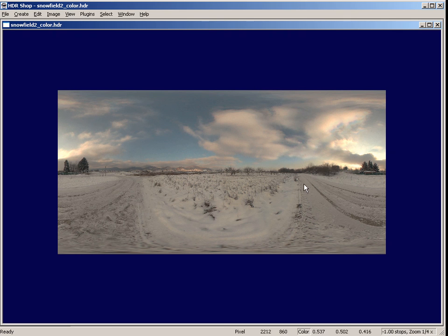Look in this area. It'll give you values in terms of floating point, which is another key factor: not 0 to 255, but 0 to 1, with 1 being white. But you'll also notice that as I approach the sun area, we're actually getting values that are higher than 1. And that is what we need to happen. As you remember, sometimes we have to take our sky and give it a multiplier of 2, well, here that information is built into the image right off the bat. That's a key factor in terms of us doing this.